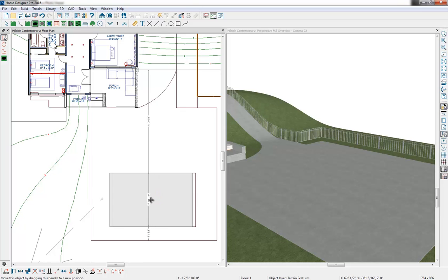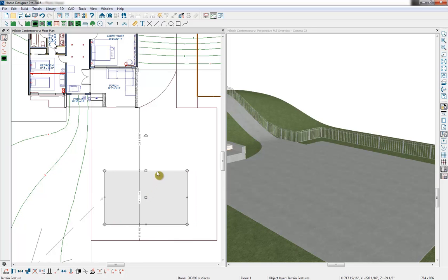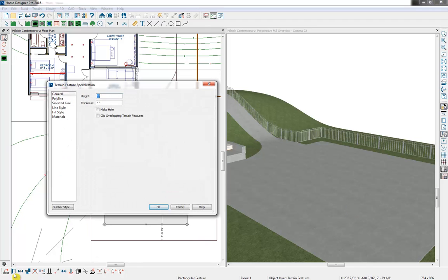And bring it over. And then I'm going to single click on our break line tool and break it just so we can modify the shape here and bring that down slightly. Alright, and you'll notice nothing is changing in our 3D view. It's because this is on the same level, the same elevation, it's the same material, so it's just being applied in the same area.